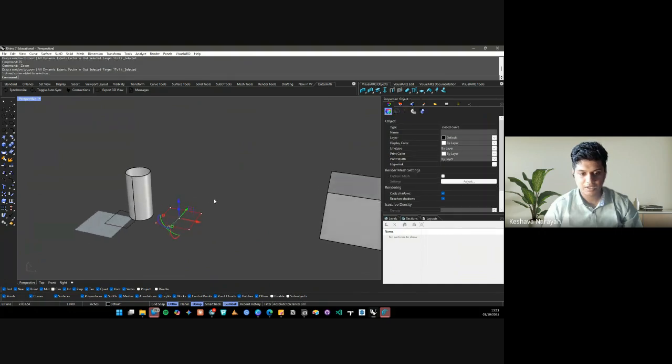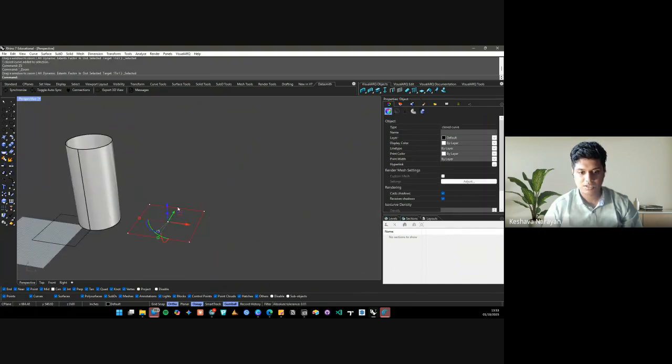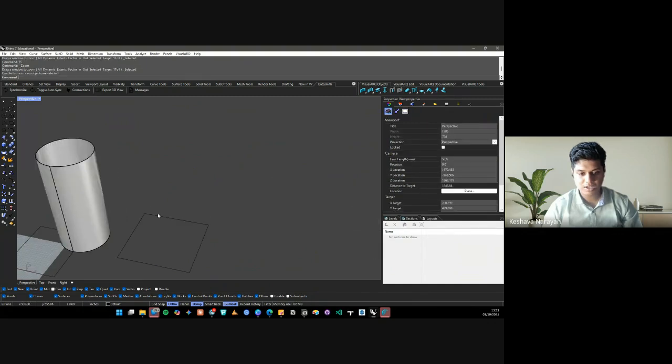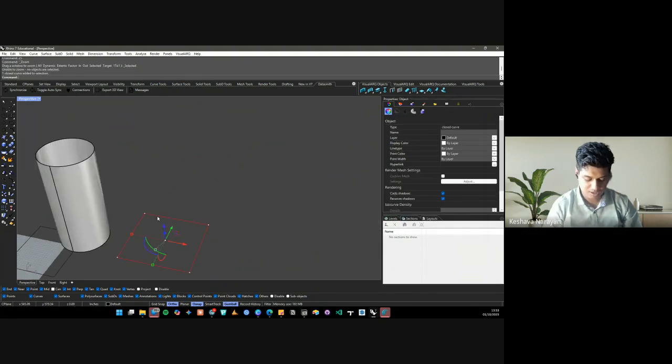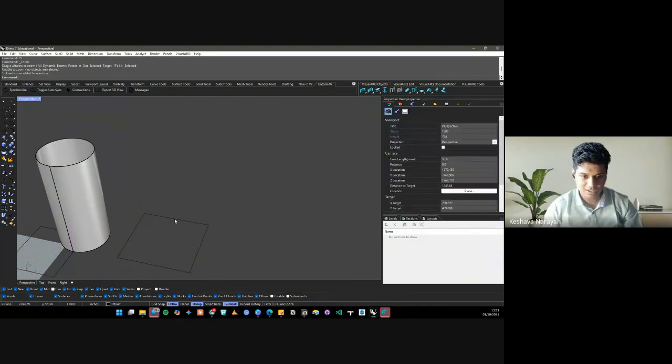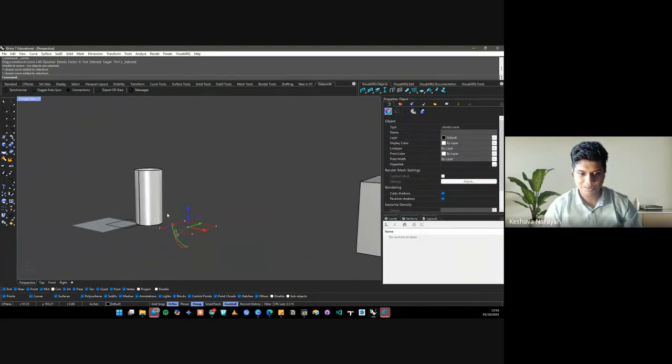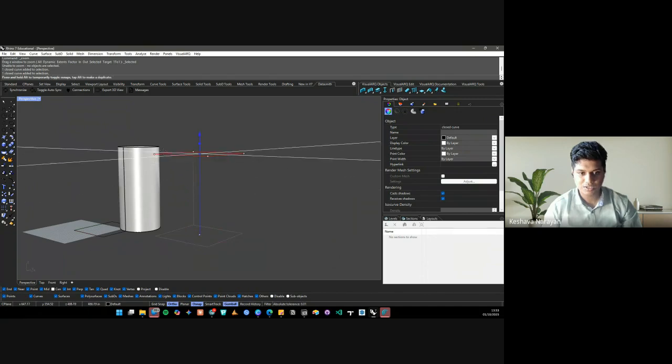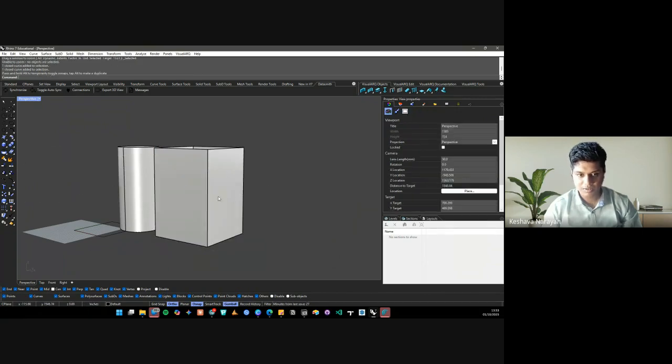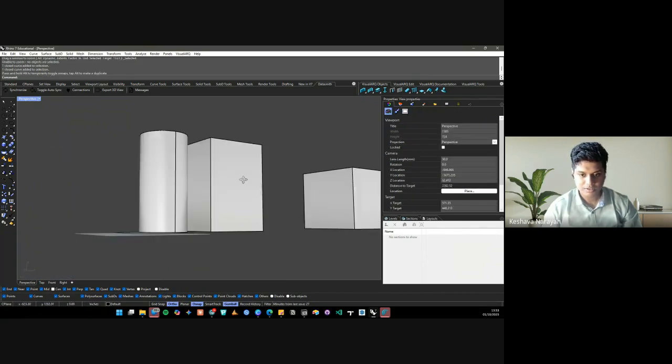Or you can also create 2D surfaces. You can click on this and type in planar. Okay, let's not get there. That's a little bit advanced. So maybe what we can do is just extrude this. Now we've already created a cuboid.